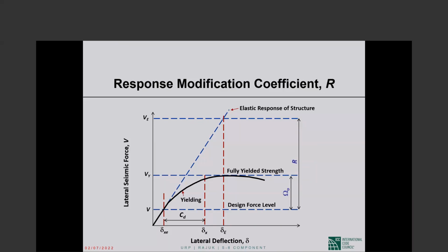We know that if the design earthquake were to actually hit, the displacement of level X would be much higher than delta sub XE, because V does not represent the force that will actually be induced in the structure by the earthquake. That is what we are designing for. But the earthquake probably will induce more forces and definitely more displacements.